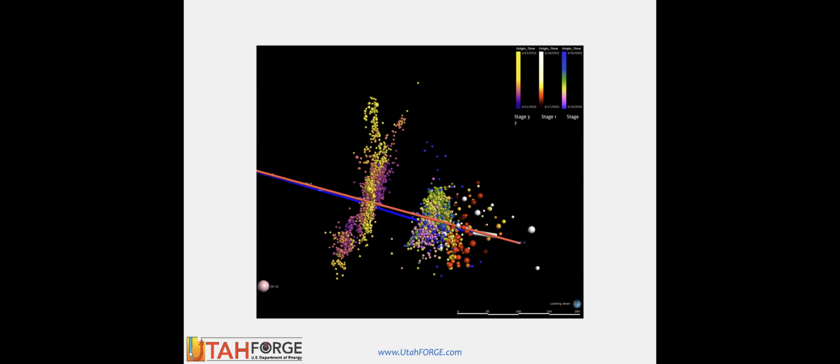Yeah, good suggestion. Because I would think that you've set up the model so there's tons of shear stimulation, and so the model is going to predict that there was shear stimulation during that period of the injection, but actually there wasn't. And I think it's very important that they tried to do a shear stimulation and there wasn't. The only way to get stimulation and microseismicity was to go above SH min, and that means they had to create hydraulic fractures, and that raises the question of how much shear stimulation is actually happening if you couldn't stimulate without creating hydraulic fractures.